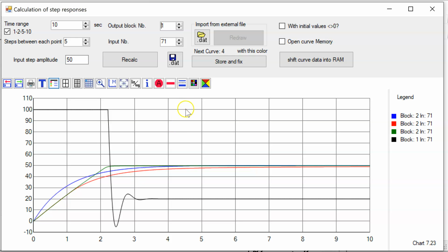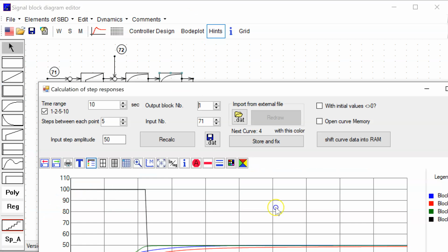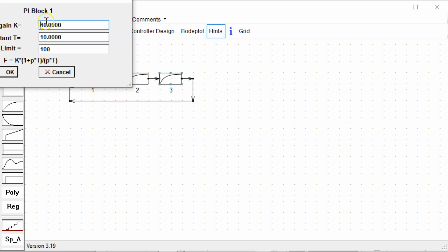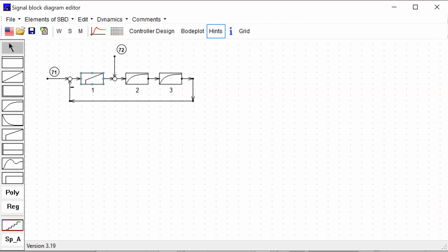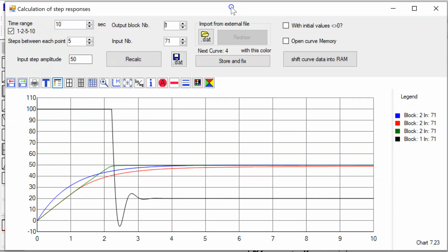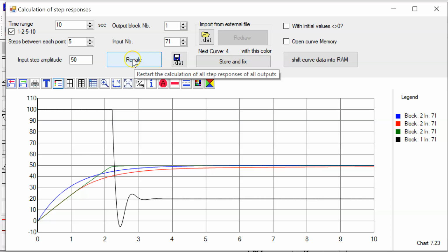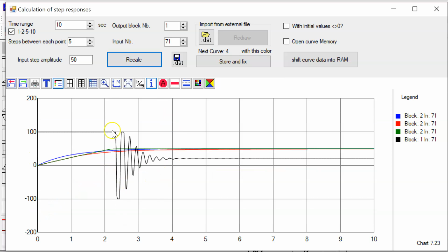in your system. If I do one step more and I increase this gain more and more, say up to 400, then you will see what happens in my situation of recalculation. Here you see, then you get a strong oscillation of the motor power signal down to a negative 100 kilowatt, means you have to brake with 100 kilowatts, then you accelerate plus 100 kilowatts, then you brake, then you accelerate. This, you see, is not that really what you want in your system.